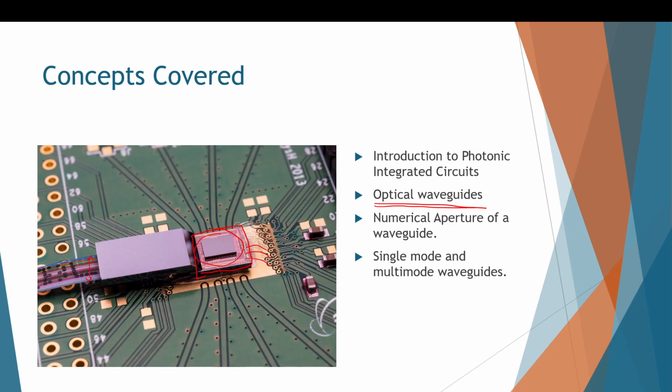For photonic circuits we also need some electro-optic modulation, or even acousto-optic modulation, which requires some electrical signals, right? These can be connected to DC power sources or RF sources based on the application. And you see these gold things, those are the metal pads. So that's how our photonic chip will look.